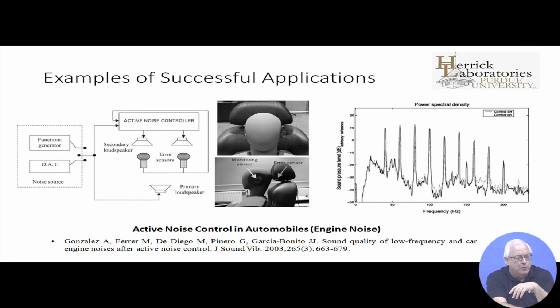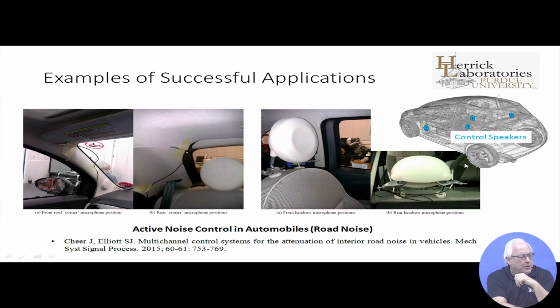Presumably this has to do with gear noise or something to do with an electric motor. And so it's very easy to generate a stable signal that is in phase with this, and then invert it to create an out-of-phase signal, which can be used to cancel the noise.